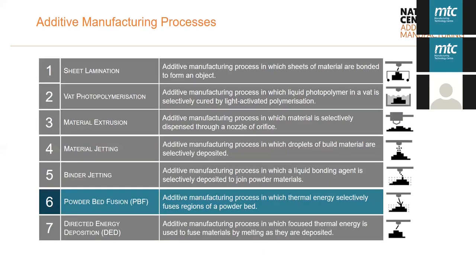It might require some optimization for powder removal. So you need to really understand how you're going to remove the powder from this implant, and also centering, so how you're going to support it for centering and to reduce the amount of warpage and distortion. But in terms of orthopedics, the high detail that you can get from metal binder jetting and good accuracy really favor that application because of the complex stuff you can do with the latticing, etc. So it's a good application for it. There are just some key areas of optimization that might be required.